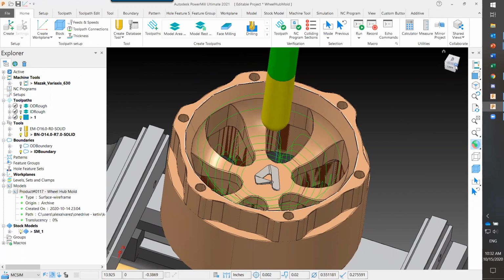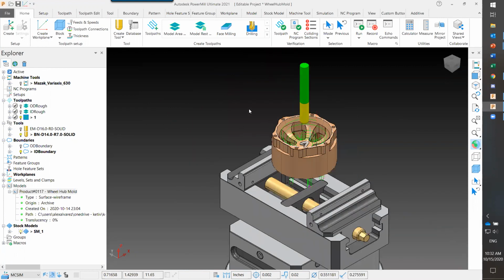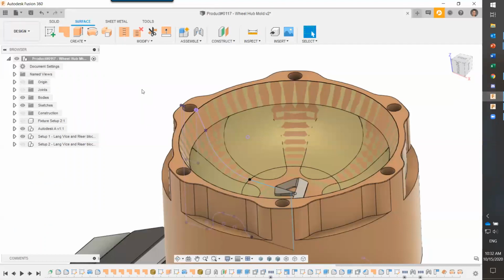The biggest thing here is making sure that the paths match, right? So if I'm going to be exporting this part out, I want to make sure that the path that I exported out to matches. Not only that, I also want to make sure that the name is going to match, right? Because if it doesn't match, then it's going to see it as a different part and it's no longer going to work, right? So you have to make sure that the name is exactly the same. So again, a couple of workarounds for that. That's something that we can talk about at a later time.